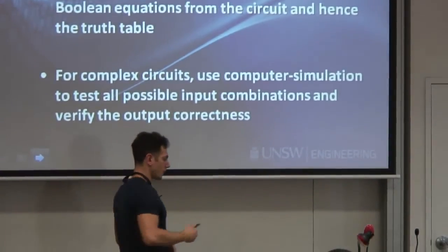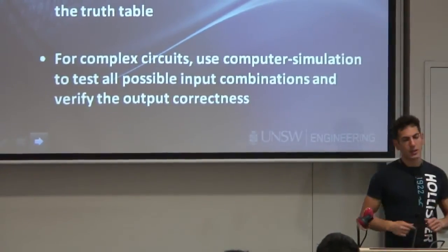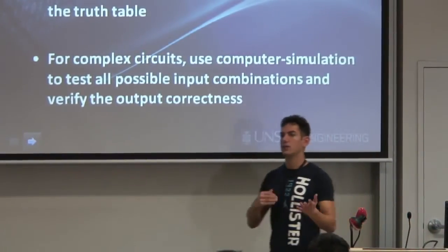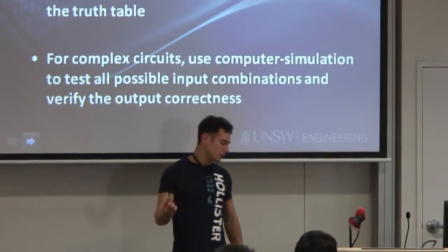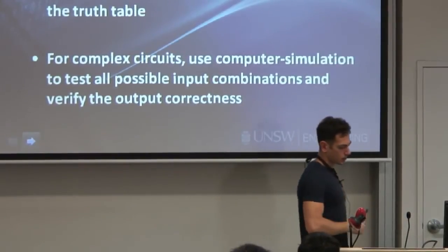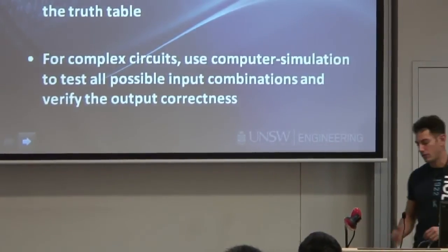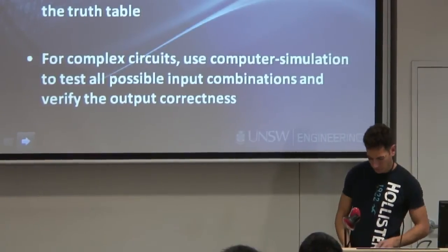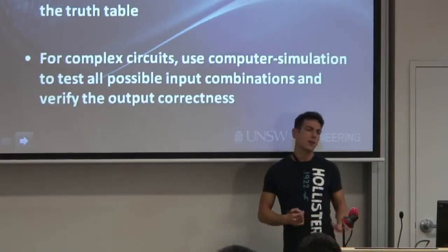We will define what the outputs should be, and then the software can run the test through our circuit and compare it with what the result should be. If there's a mismatch, then the software will alert us, and then we can go and try and debug what's going on. So that's sort of the way to go about doing this.